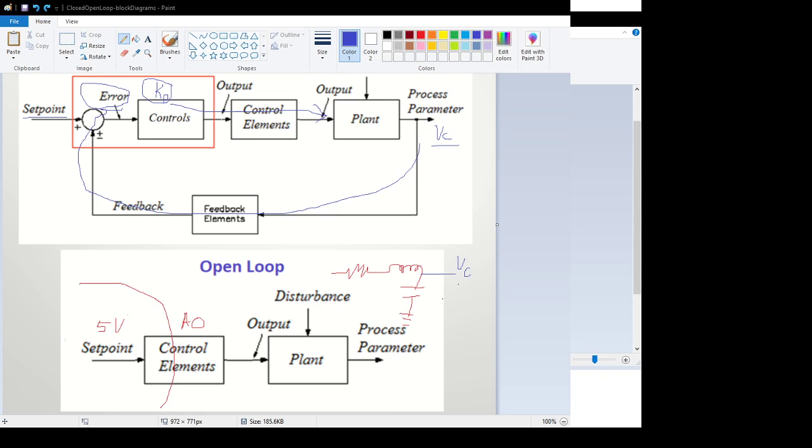The first thing I do is have my 4-position selector switch to select whether the gain is going to be 1/2 or 0.5 gain, gain of 1, a gain of 2, or gain of 5. Okay, so what it's doing is just doing a move of that gain tag into my KP tag, which is my proportional gain that I'm actually going to use in the controller.